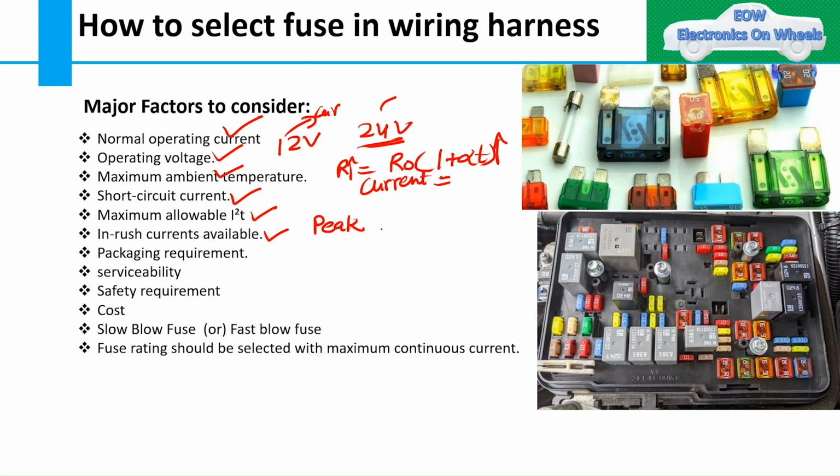We have slow blow fuses and fast blow fuses, so which type of fuse you have to use? Among slow blow fuses you have mega and midi fuses. So you have to take care of the transient conditions when you are selecting the fuse. Then the packaging requirement.